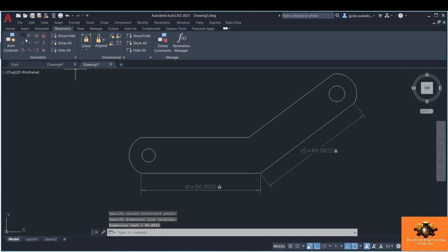And that's good. Let me make some geometrical constraints just to show you how the whole drawing will behave as one. Let me assign these constraints to all the lines. Okay. Additionally, let's assign the same center and radius to the circle, and let me make these two lines parallel. Okay, I think it's enough.